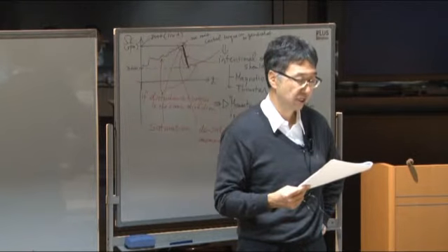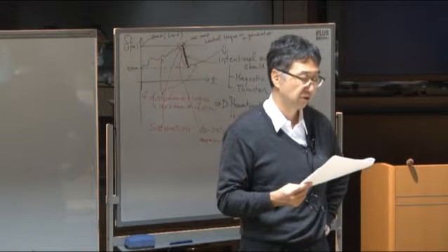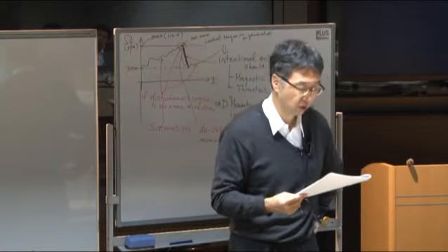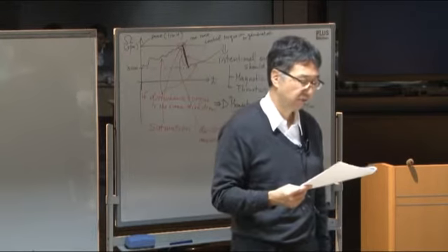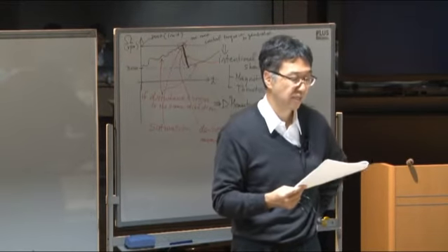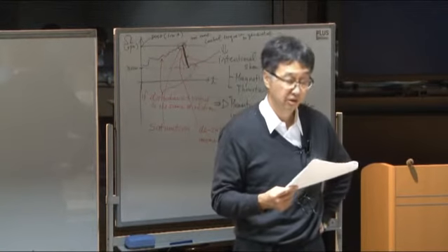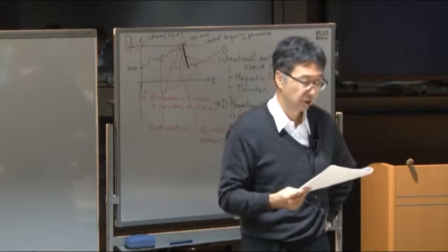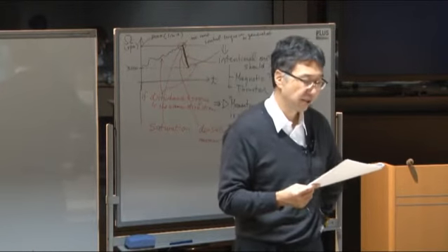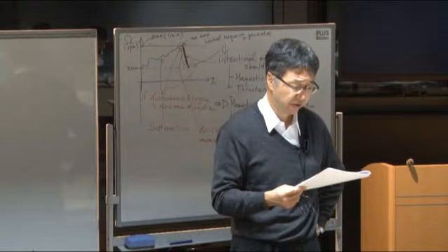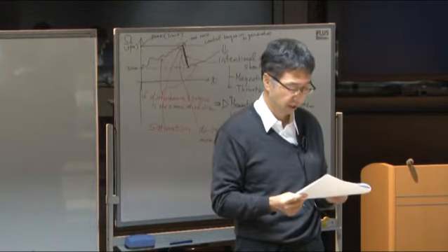If you use the ion thruster, you can get a very high orbital maneuver or attitude change capability with very small fuel. But the force itself is very small, about 1 millinewton or less. Very small force, but it is very effective and efficient. The other two are configurations of the thruster system.